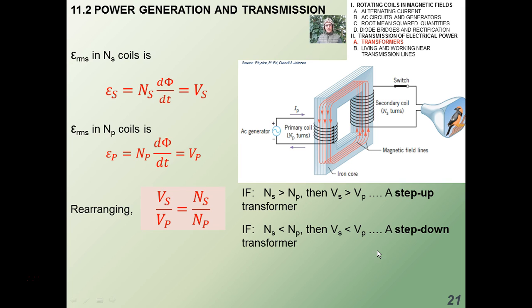So a step-up transformer, again, you would use it, say, if you had a device that you bought in, say, Great Britain or something that needs a 220 volt potential difference to work, and you're using it in North America, for example, you would use a step-up transformer taking 110 volts from your plug here, or in North America, and you would actually transform it to 220 so that you could then use your device. Step down is the other way.